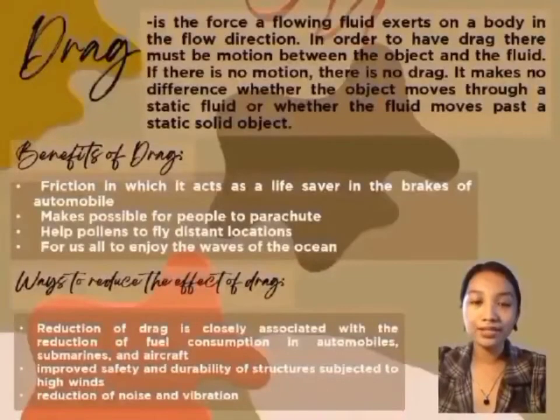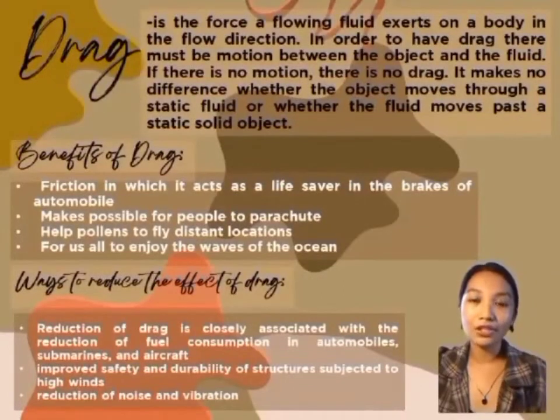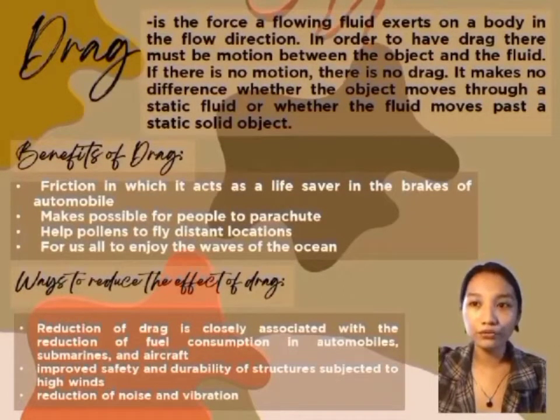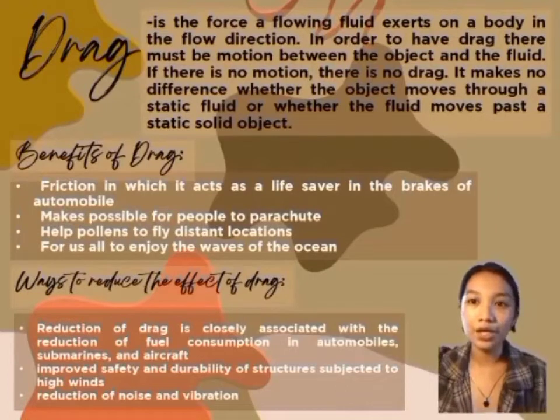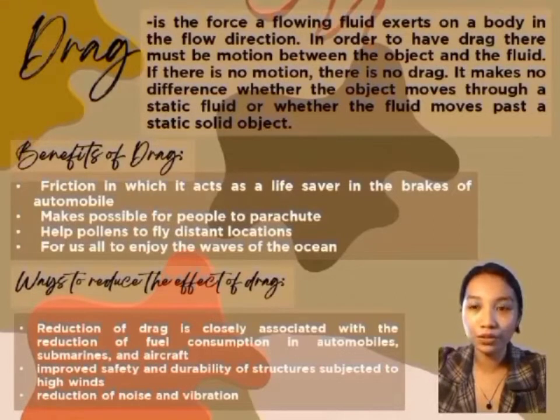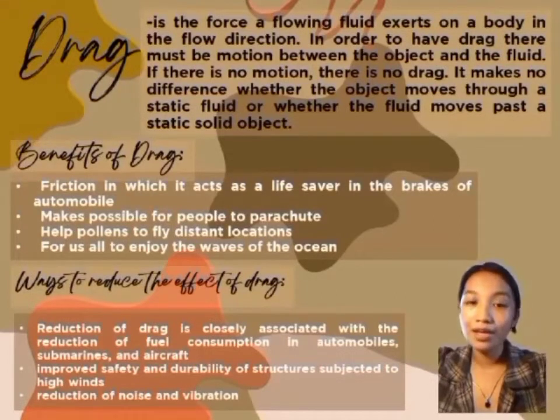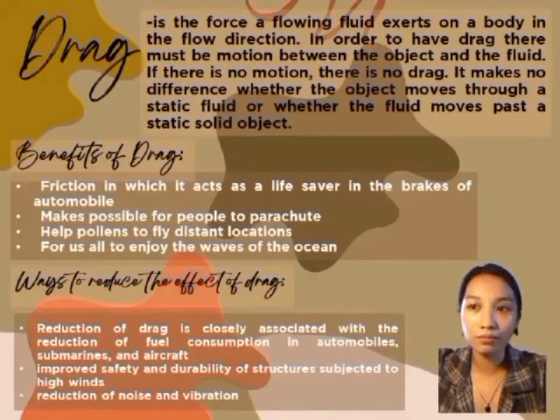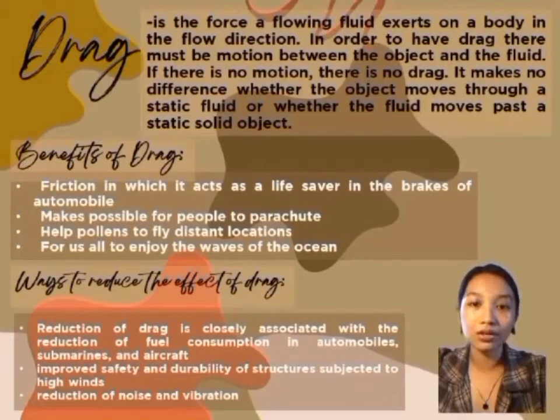So now, let's talk about drag. Drag is the force a flowing fluid exerts on a body in the flow direction. In order to have drag, there must be motion between the object and the fluid. If there is no motion, there is no drag. It makes no difference whether the object moves through a static fluid or whether the fluid moves past a static solid object.